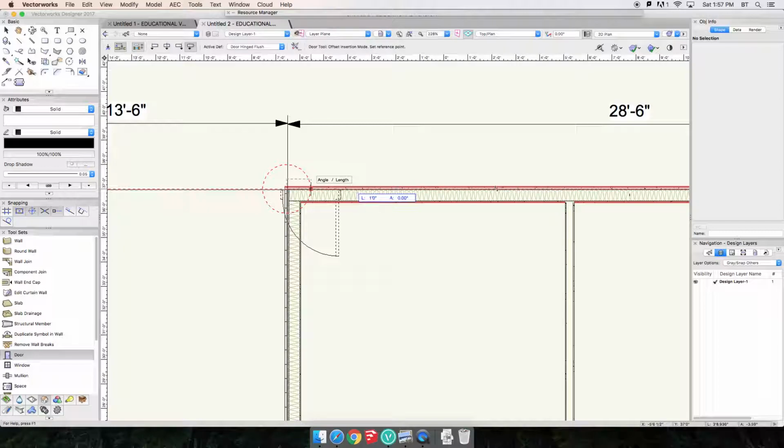And now what's happening is it's inserting it, it's 1 foot, but it's from the center of the door, right? So sometimes, and I can see it's up this custom align object origin mode. So we can also, and then moving my cursor, I took it out of that. So I can tab in 1 foot and angle 0, but I can toggle with my O key, and now I'm changing where I'm specifying, inserting that door to.